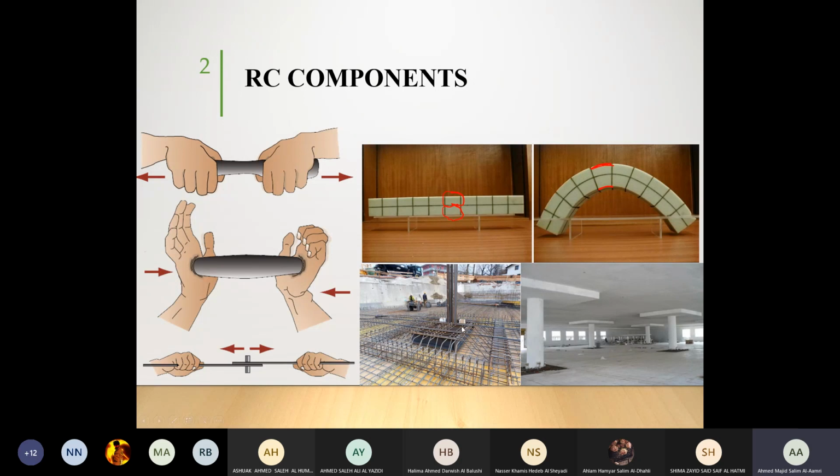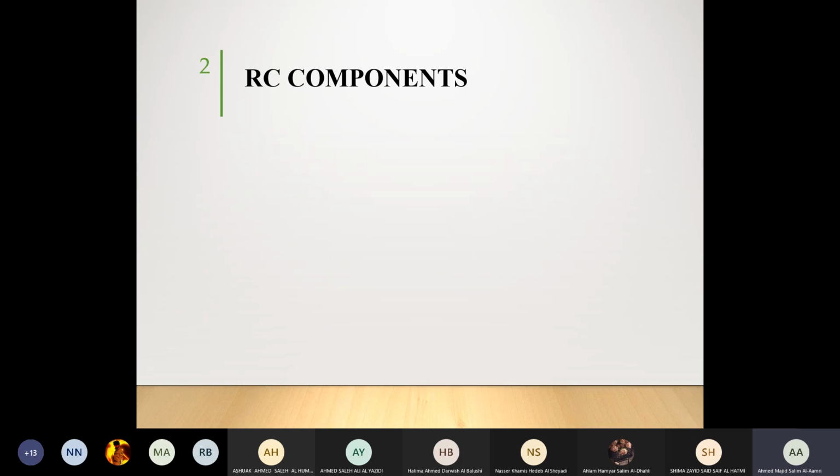Either we can have a plate here to stop the area which is weak or wherever there is high loads. And in terms of flat slabs, we can have either a drop or a column head as well. So these are the first things that we have discussed about reinforced concrete. The other things we said, if you remember, there are two things which are affecting our steel. One is water, another one is fire.